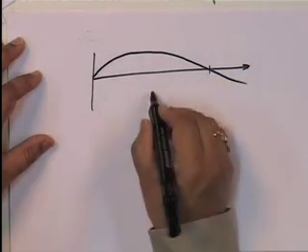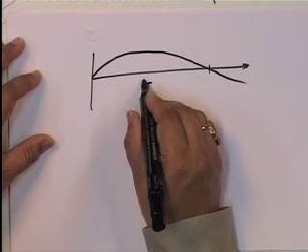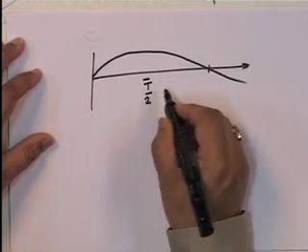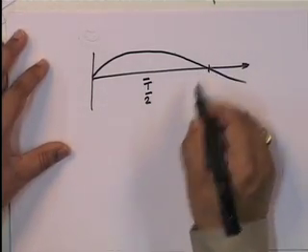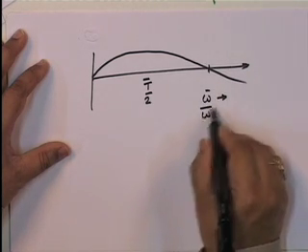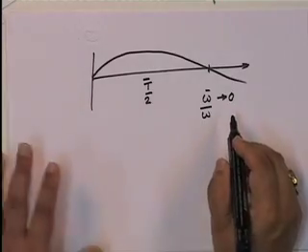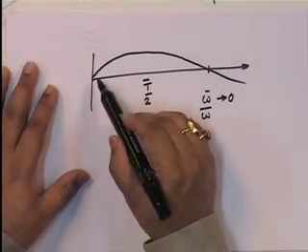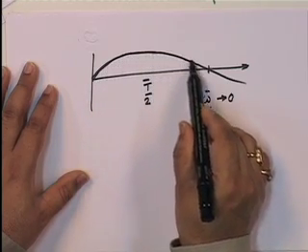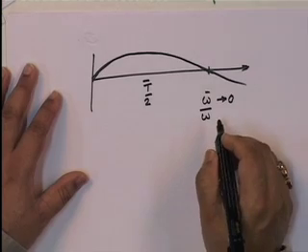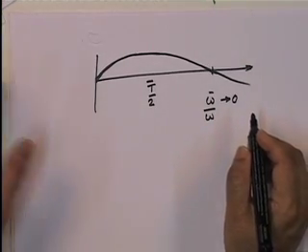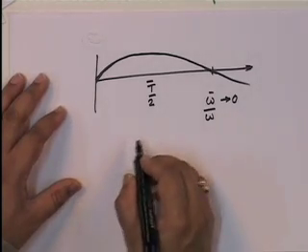Relative to the structure, this is T bar by 2. This is half cycle, so it is T bar by 2. Okay. So, if you have omega bar upon omega tending to 0, it basically means that as far as the structure is concerned, this load is a very, very slowly varying load. If it is a very slowly varying load, what happens? For all practical purposes, if we look at it,